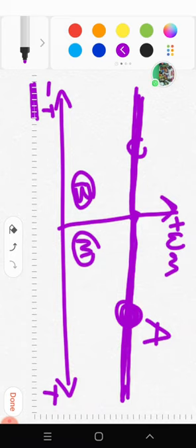So if by any means the speed of the machine increases and goes beyond no load speed, see, the speed at this point is more than no load speed, whereas normal operating speed is less than no load speed. So the machine runs with speeds more than no load speed, higher speeds. In that case, there is a possibility of negative torque.